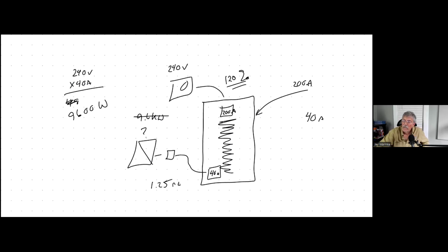the wire size. So maximum of 40 amps doesn't mean you can run 40 amps over it. We would have to take 40 amps, we would divide that by 1.25. That's the safety margin. And that will give us 40 divided by 1.25, 32.